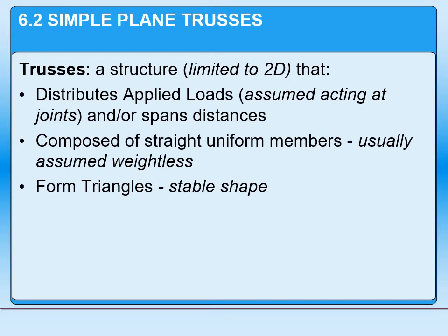On the other hand, if you take a look at a square or a pentagon or anything with more than 3 sides, the actual structure can buckle and generally will fail at a much lower load. And you oftentimes see in square-shaped structures a support member going diagonally from two edges to form a triangle. Because again, what we're looking for in almost all of our structures is that they are stable and strong.